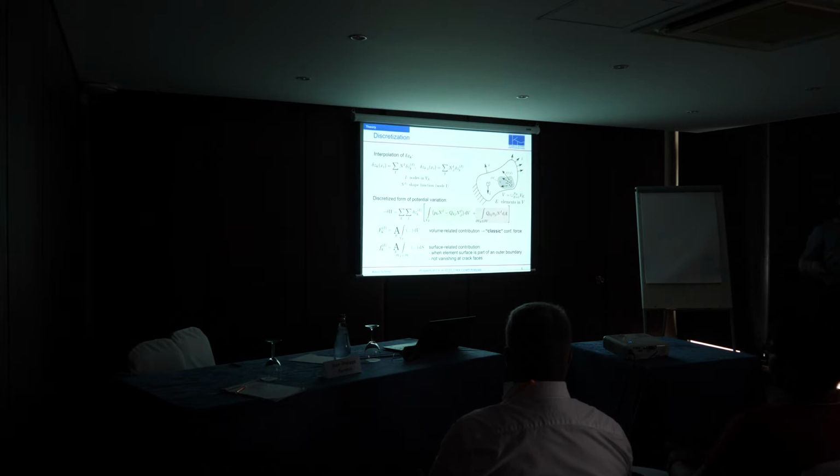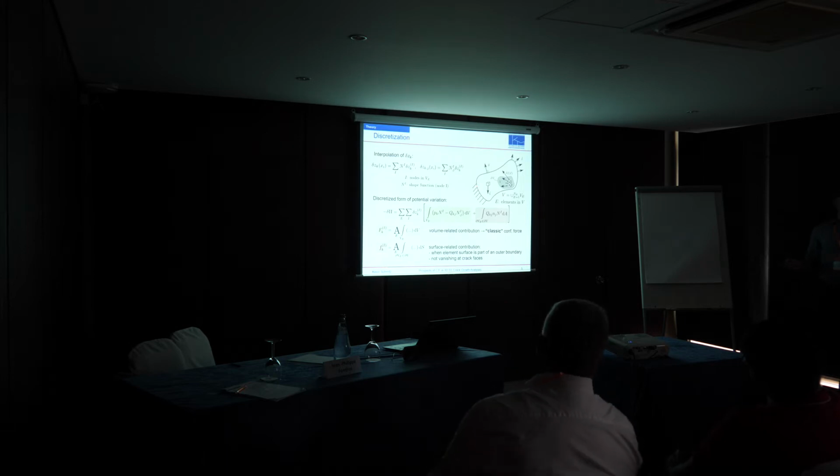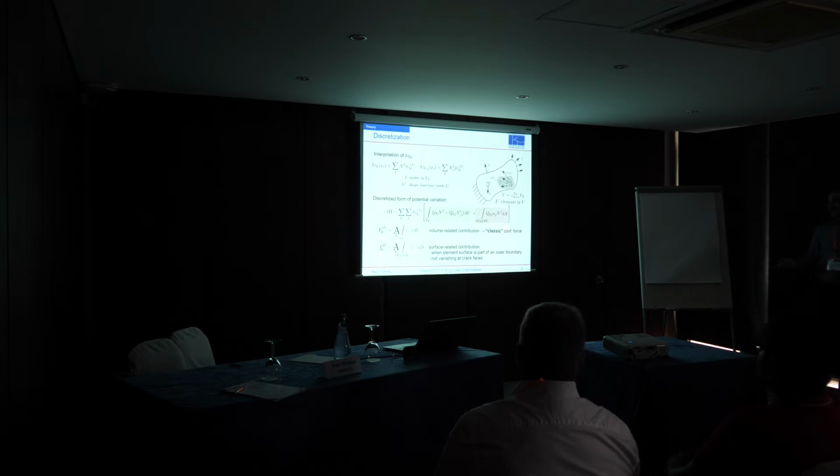This is the classic configuration force that is often used in finite element frameworks. But we also see a term arising that relates to surface contributions, meaning that this part is relevant when an element surface is part of an outer boundary of our problem. This also means that this part will not necessarily vanish at crack faces. So we have to take this into account in some special cases.